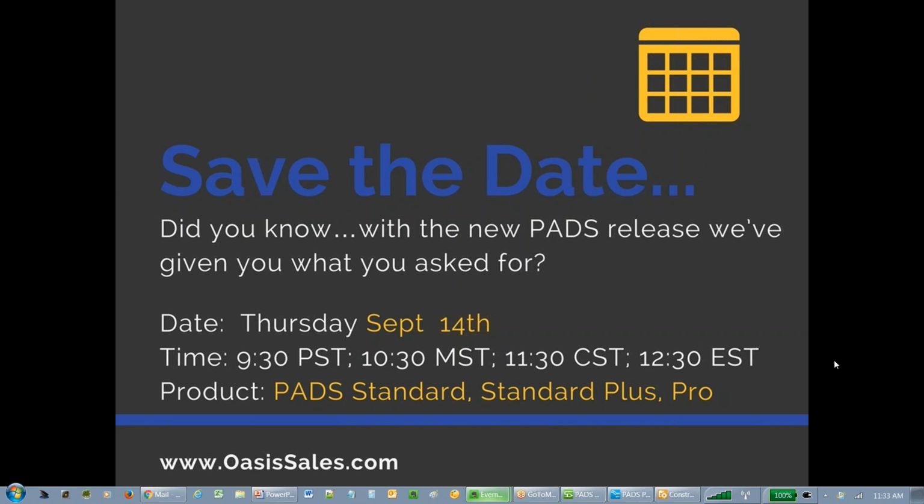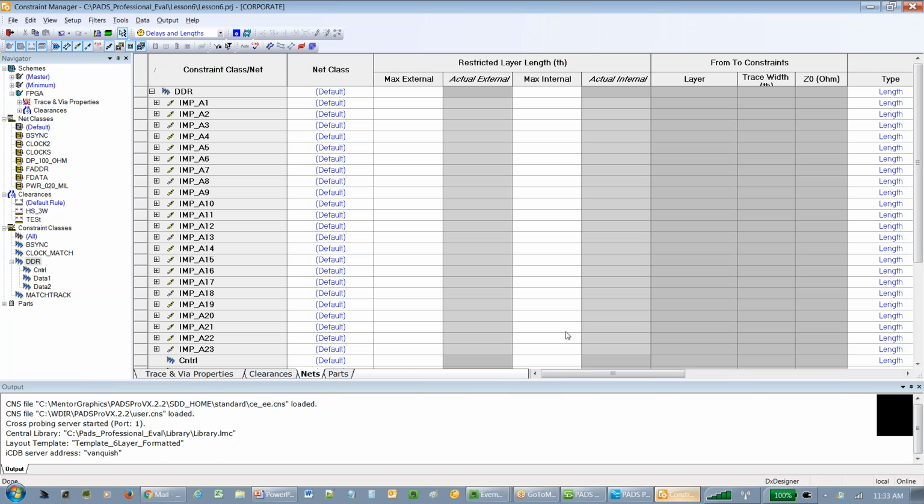Okay, let's see, I think I got another question here. How to keep track on the constraints order automatically, save as a new revision. No, the Constraint Editor does not keep constraints from a revision perspective. It does remember them. So there is a rollback feature in the tool. So if you ended up making some constraints and you wanted to roll back to the last time you opened the tool or the design, you could use the rollback function, but there's no revision check-in or revision specific history that you could tie into at this time.